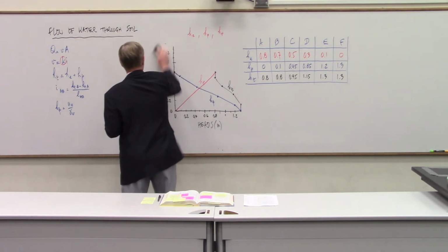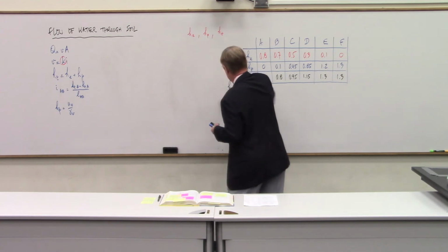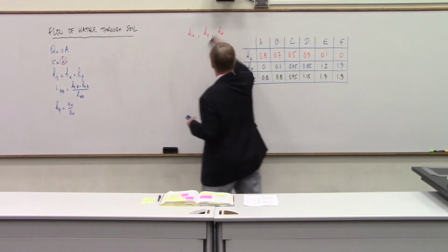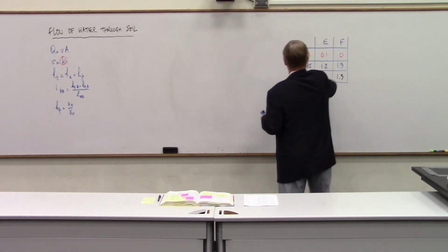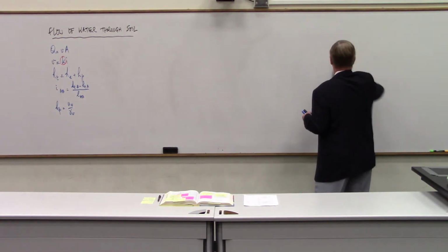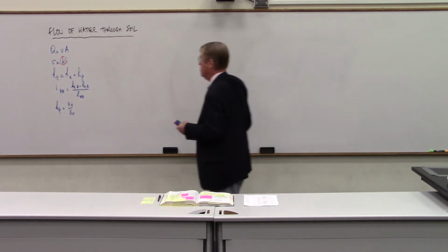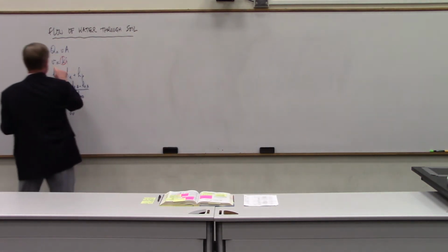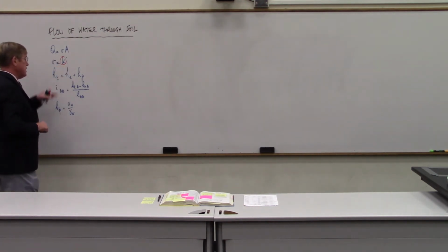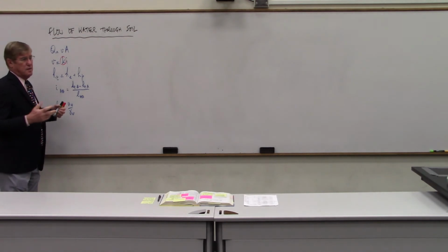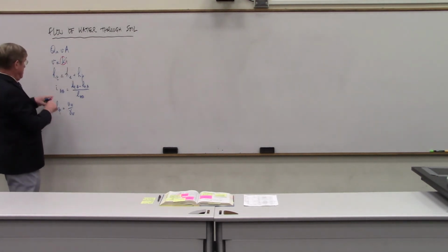And K varies dramatically. You can imagine that the difference between a gravel and a clay will be very large in terms of how fast the water goes through. Because if you think of Darcy's law, V equals Ki, and I told you i does vary, but it has no units.